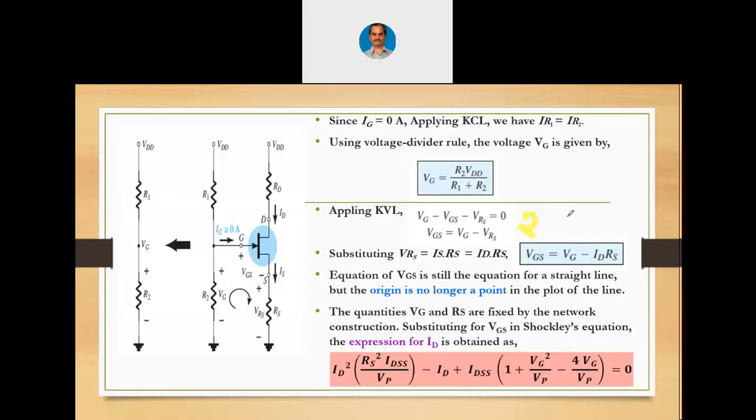2 volts and 1 volt and 1 volt. Now Rs is increased, ID reduces. Now Vg remains 1. Even though ID is reducing, the product of ID into Rs is going to increase, because Rs is in kilo ohms and ID is in milliampere. You may again say that milli and kilo will get cancelled, but the change in Rs will be much larger. So that way this product IDRS is going to increase. Now let us say IDRS is going to increase by 1.5.